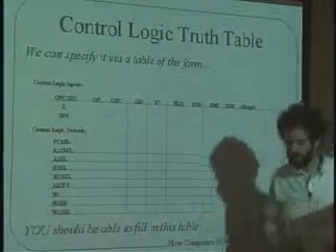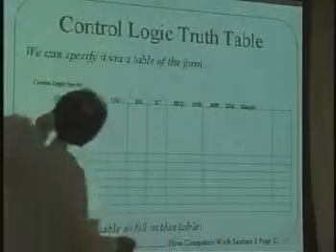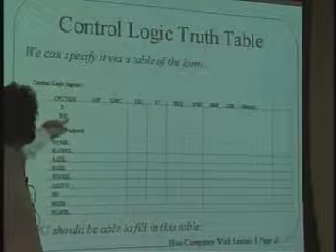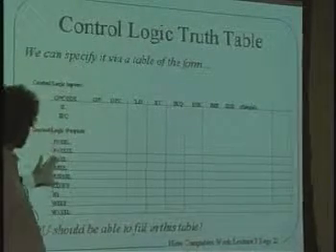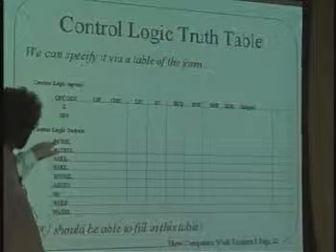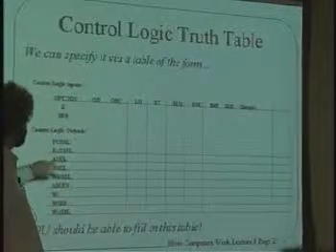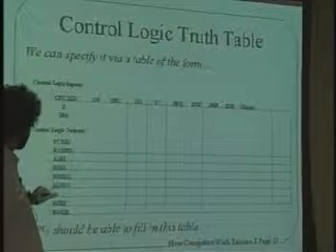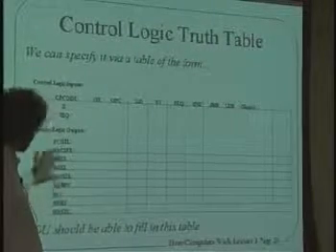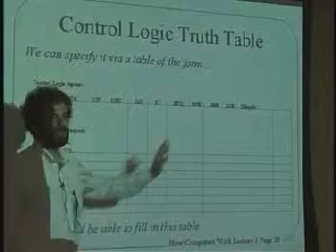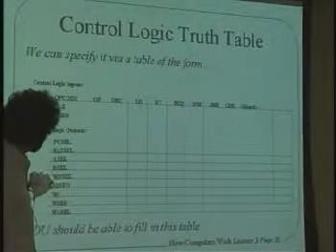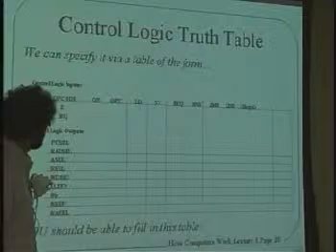And given those opcodes, given whether or not the thing that was testing whether the contents of register A is 0 or not 0, and given whether or not there is an interrupt that we're trying to do, and again, we're not going to talk about this quite yet, depending on all of those things, we will want to control these outputs being the selectors, PCSEL, RA2SEL, ASEL, BSEL, and WDSEL. All of these things will be controlled in a different way depending on what kind of opcode we're trying to do. And then finally, the ALU function will also be controlled depending on what we're trying to do.